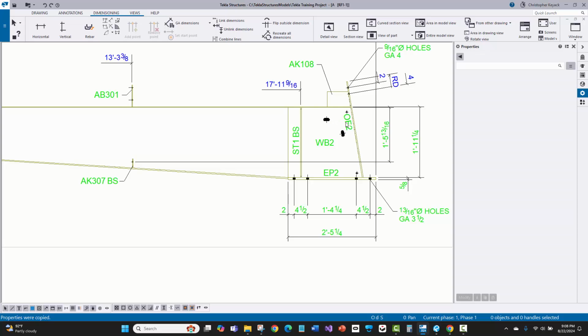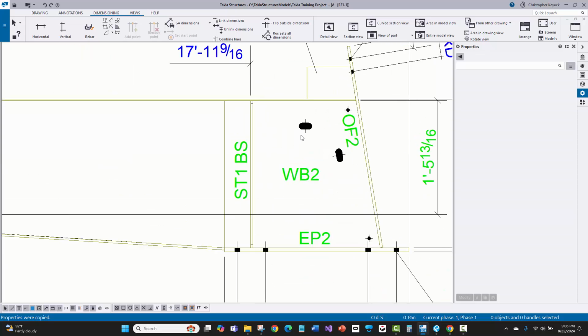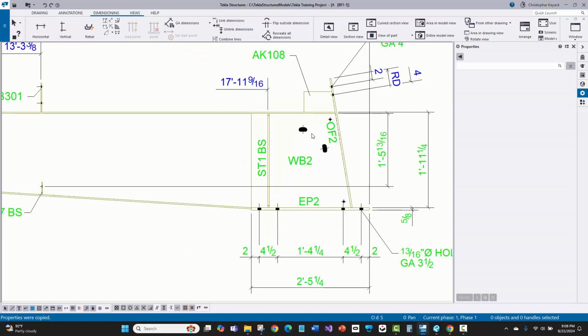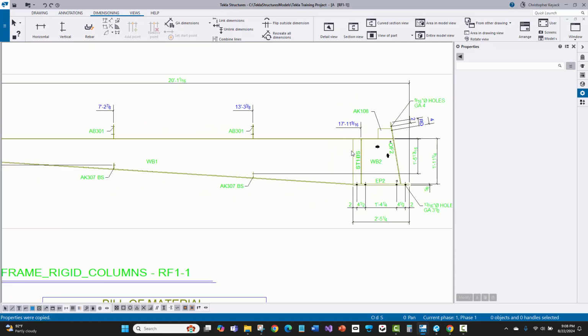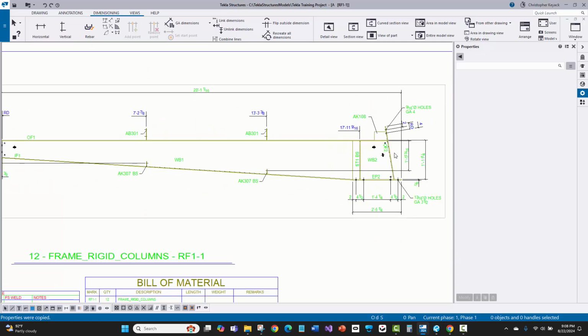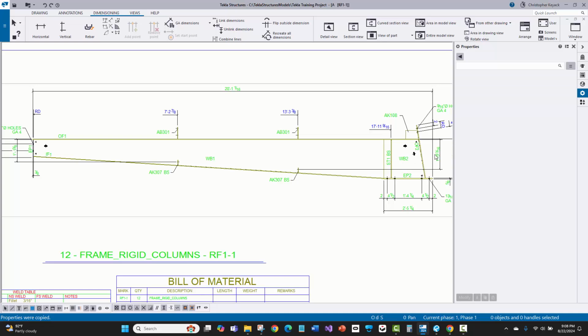Now, because I do web drawings usually, I don't have the dimensions to the webs, the slots and the holes. So it looks like there's some drainage holes on this particular customer's rafter and column. And then there's also the slots here. And I just don't have dimensions there because I'm making a web drawing and all that information is shown there. And then this is usually burned on the plasma table. So really, mainly what I need to see on the assembly drawing is just to show how those web parts are basically joined together and the orientation of those.